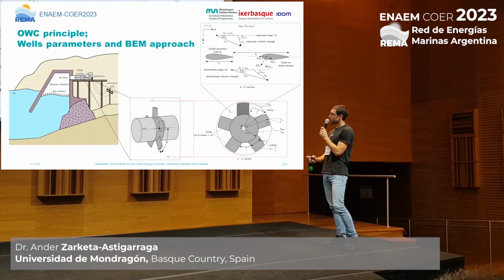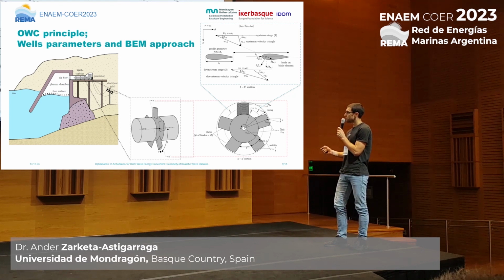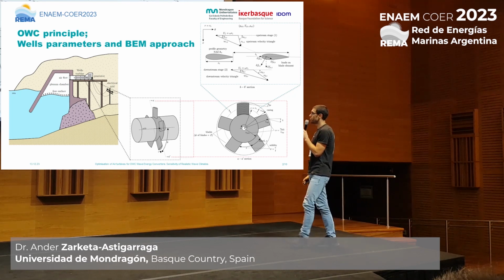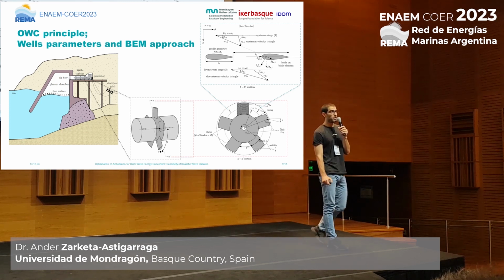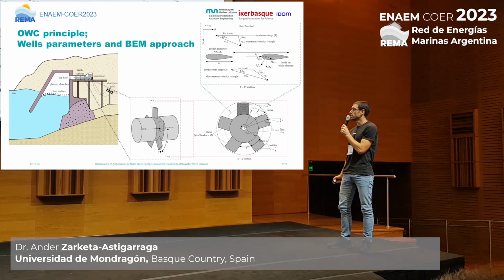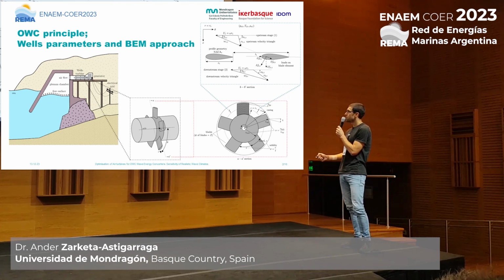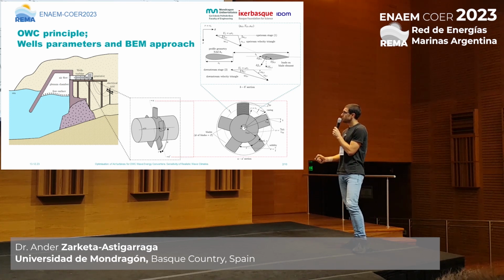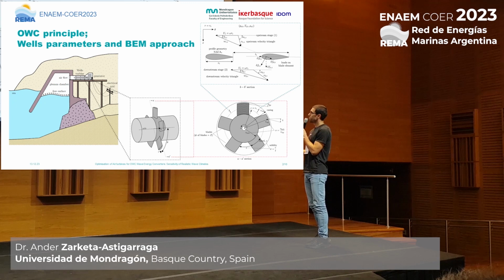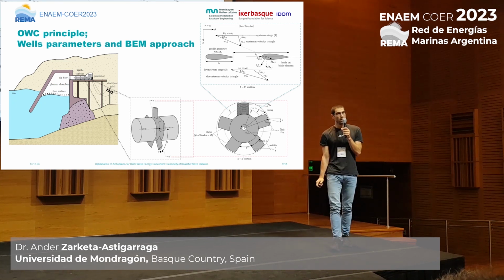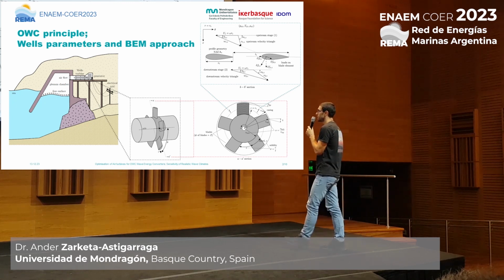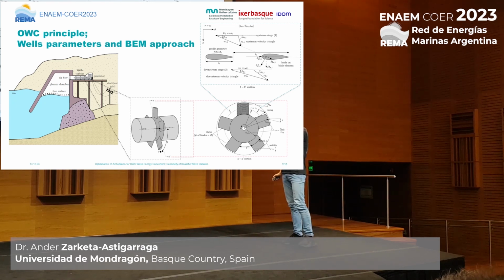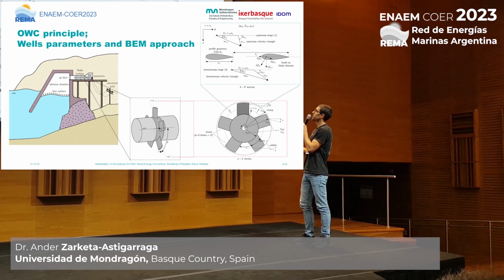For the other part, this figure also serves the purpose of showing the foundation of the blade element method that we are adopting as a solving strategy, via this radially split blade. We split the blade radially for discretizing it as in a simulation, and we consider that each blade element constitutes a two-dimensional linear cascade like the one shown upside.